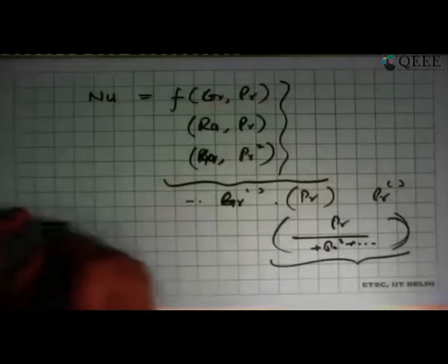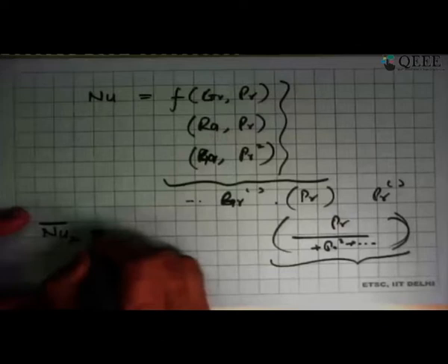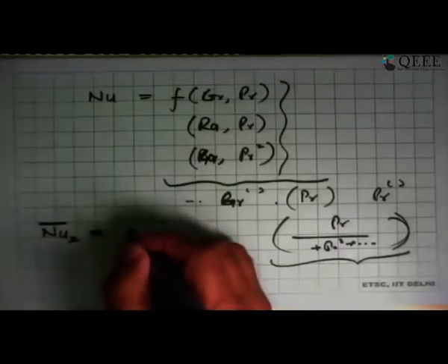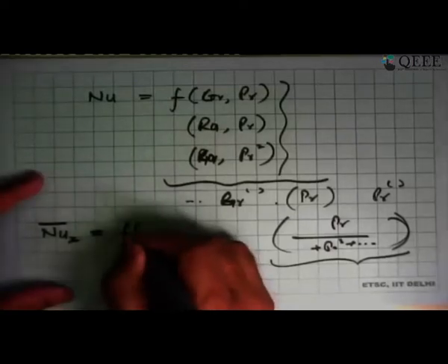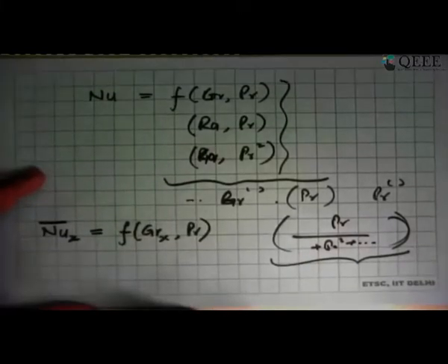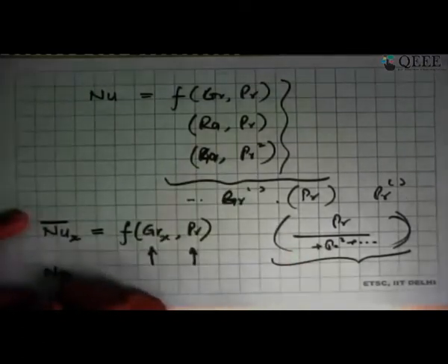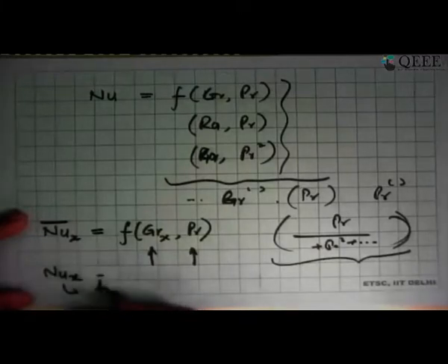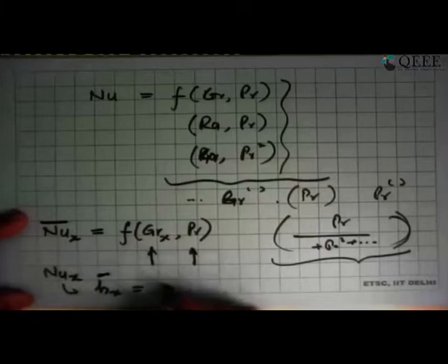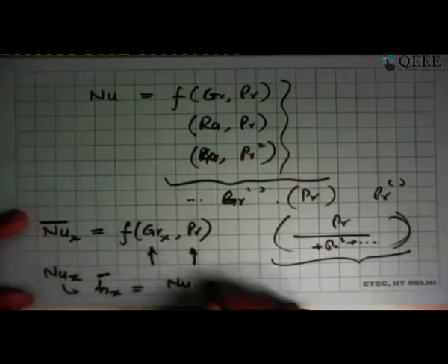So that's where we want to get the solutions for a vertical plate. How do I get the local heat transfer coefficient? You look up the correlation tables and say it's a flat plate, an isothermal plate, or an iso-heat-flux case, whichever those cases may be, and you'll get some function which says this is related to the Grashof number and some Prandtl number. That means in that problem, with all the data you need to calculate Gr_x, you calculate Pr, use that formula, you get Nu_x, and from there you say h at x is equal to, from the definition, Nusselt number into k by L.